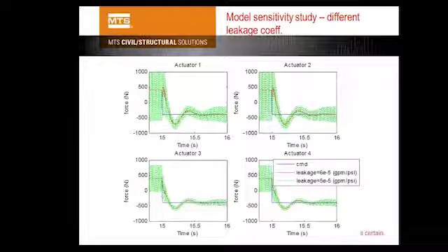Another parameter I want to show here is the leakage term, the leakage across the piston. That's one thing I found throughout this case study. It's very interesting because in the beginning I didn't think about this term at all. I thought, leakage, maybe for global dynamics, why do I care about that small parameter? But eventually we discovered it's actually very sensitive how you select this leakage term.